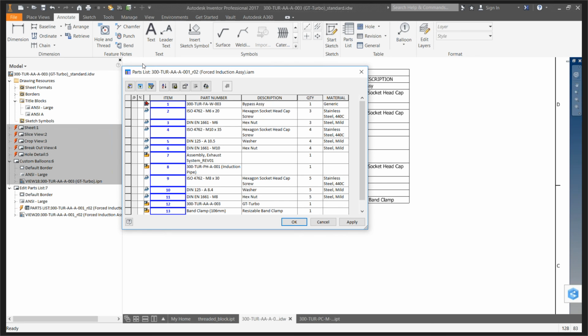By default, the parts list doesn't tell you that. There's a very simple, very easy workflow that does that. So if that's something anyone on today's session is interested in, we can put together a short 5-minute video that shows you how to reconfigure your parts list to give you quantity and cut lengths. Yep, I know that's a big deal for a lot of our Frame Generator customers for sure.